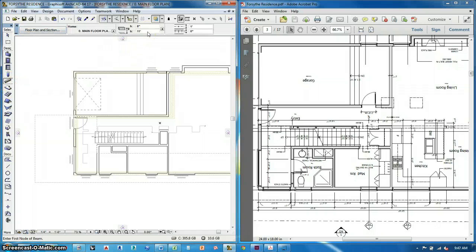And then up here I can do the same sort of as walls and stuff. I can define the height of the beam, which I'm going to set at 1 foot. And I'm going to place the height of the top of the beam. So it's going to be top of the beam to the floor. Top of the beam to the floor is going to be 9 foot 1 1/8 inch. And it's going to be 5.5 inches wide. That's how that beam is going to go.